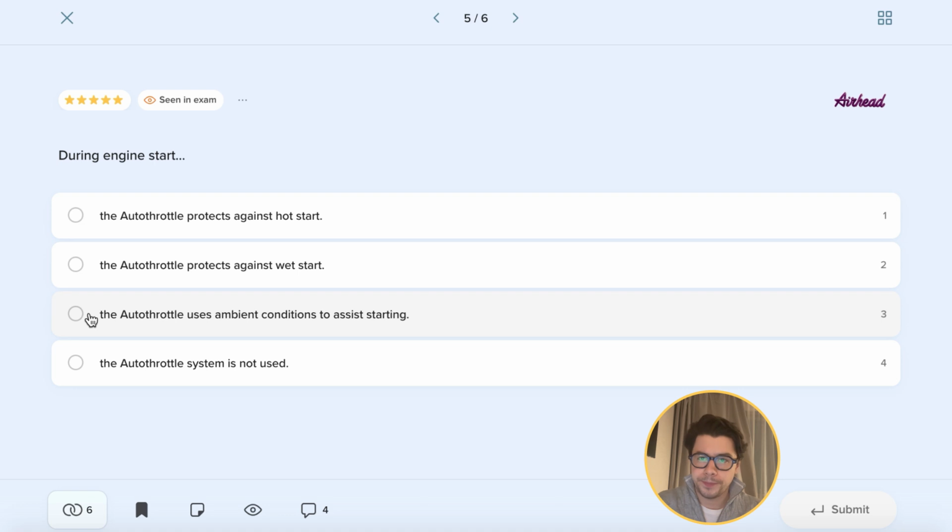All the procedures that have to do with the starting of the engine and shutting it down will be managed by FADEC. So this full authority computer that is located on the engine will manage the exhaust gas temperatures, the engine start, hot start, the engine shutdown, engine restarts, and fuel flow, and maintain a safe operation throughout the flight and throughout the engine start.